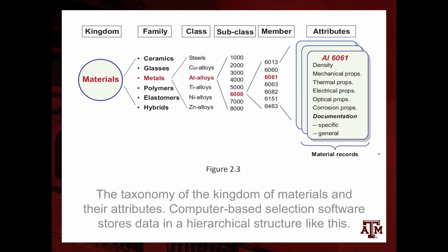So even within the metals and alloys, we can be talking about aluminum alloys, titanium alloys, steels, nickel-based alloys, and in each of those alloys, you will find different series and series numbers. Those usually have relatively different compositions. As we mentioned before, an alloy could consist of 10 or more elements. And then each of those series will have different properties and data sheets. In many cases, each of those series is optimized for a specific environment and or a specific range of temperatures.